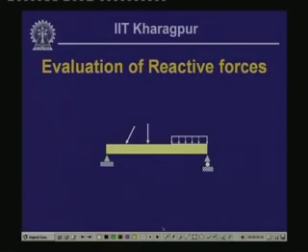Now, based on these discussions, the first step in the analysis or evaluation of the internal forces is to evaluate the reactive forces. Whenever a beam member is to be evaluated for the stresses, we will have to find out the internal forces. For evaluating the internal forces, the first step is that we will have to evaluate the values of the support reactions, or the values of the reactive forces.